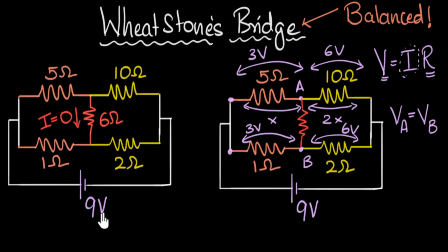Does that make sense? Isn't that wonderful? The whole idea is when the ratio of the resistances are the same, the voltage also gets divided in the same ratio, and therefore these 2 points will end up with the same voltage, making sure there is no potential difference.